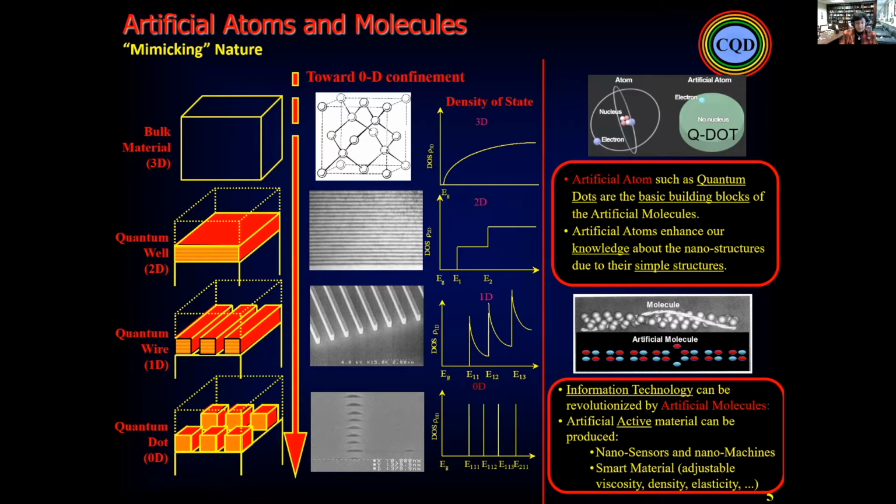What is the future at this time is if we use quantum mechanics and go to low dimensional structures: 2-dimensional confinement, 3-dimensional confinement, quantum wires, quantum dots. In this case, we can make quantum infrared lasers and detectors much more efficient and, again, independent of the temperature.